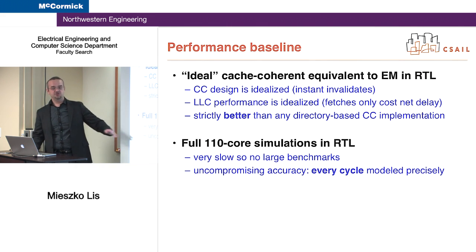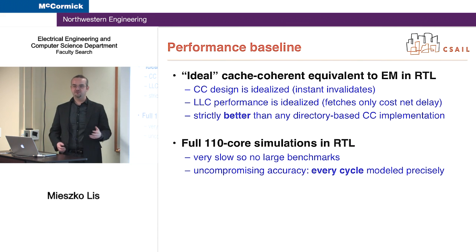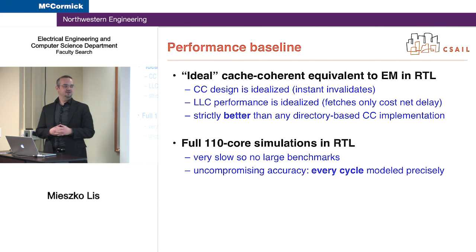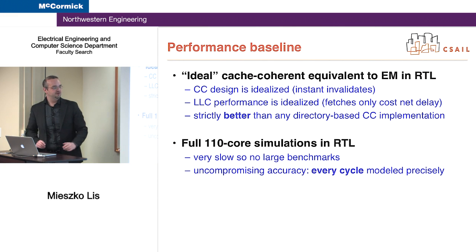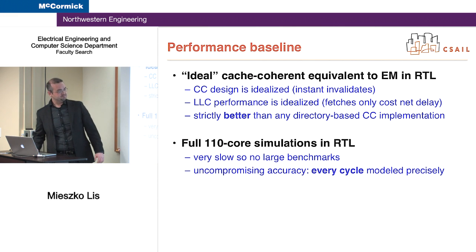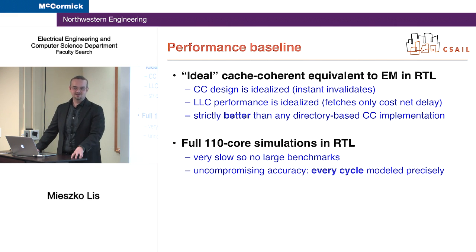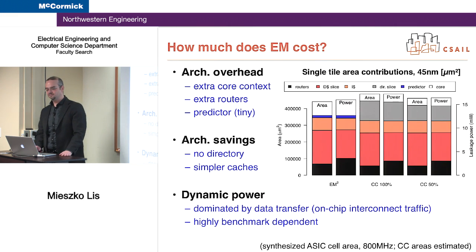And our simulations are in RTL, basically because our architecture is so different from others that to be really credible, you need to model everything at cycle accurate level. And we had all this RTL for the chip already, so it was natural to compare it. The disadvantage is that it's very slow, so the benchmarks by necessity that I'm presenting are very small. On the other hand, it's uncompromising. There's no argument that this is actually what is happening in the hardware.